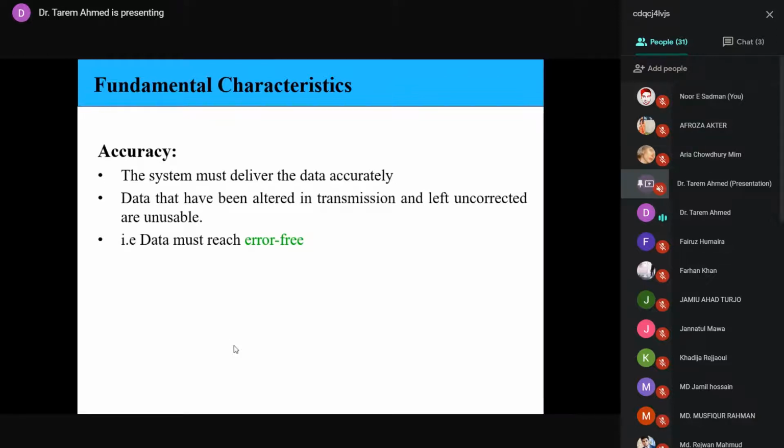Now, suppose your line is very noisy. Suppose your distance is very far. With absorption, your 5-volt has now become a 2-volt. We keep on getting absorbed at every link. Suppose it has traversed through multiple links. Suppose a 0-volt has picked up noise along the way, it is also now 2-volt. Or it is also now 2.4-volt. So now the receiver is in trouble. He cannot be sure.